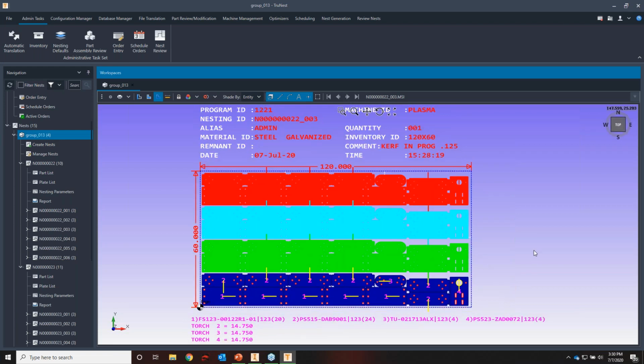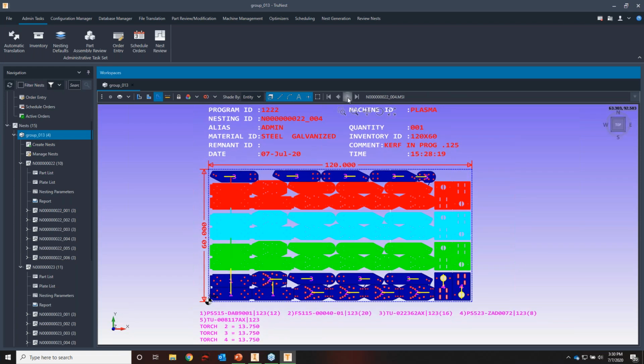And again, you'll get some results that are in somewhat strips across the plate, but that doesn't mean we won't do some torch reduction and part integration as well, if it's more efficient to do so. For example, like this one. In this case, we've used all 4 torches, and at the end, we found we still had some room on the plate to fit some more parts, so we actually put them at the top of the plate, and we're going to reduce down to just that 1 torch and process these particular ones.